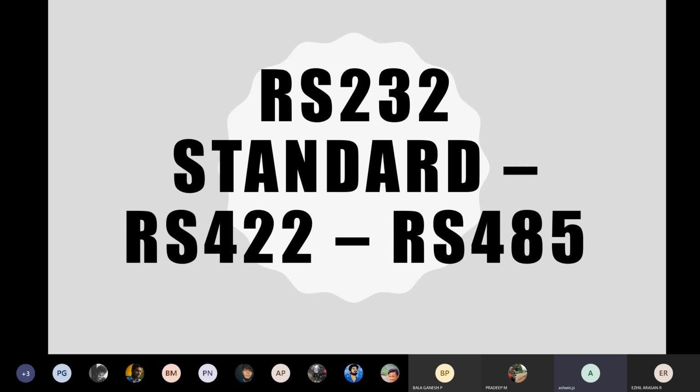So if you give idle mode, in the sense the clock pulse will be stopped, and the interrupts, the timers, the serial interrupts and that, they won't work. So that is idle mode.